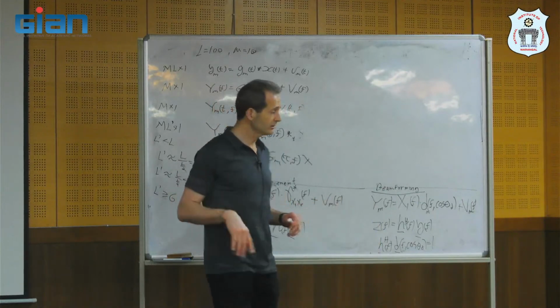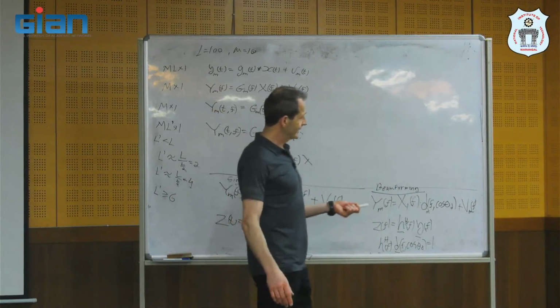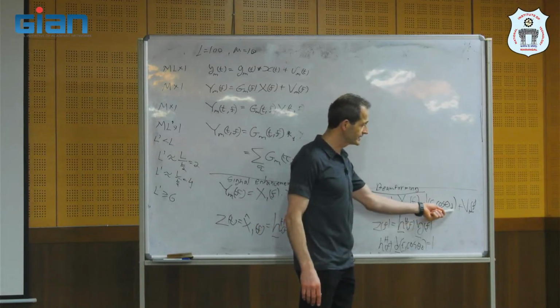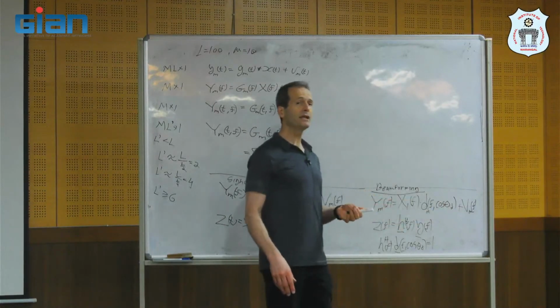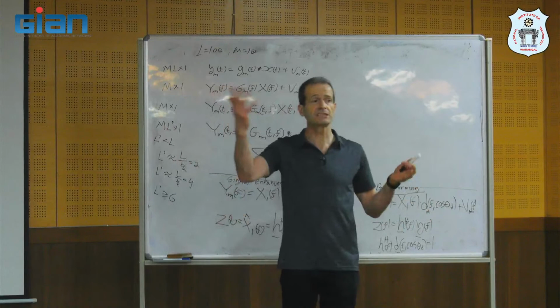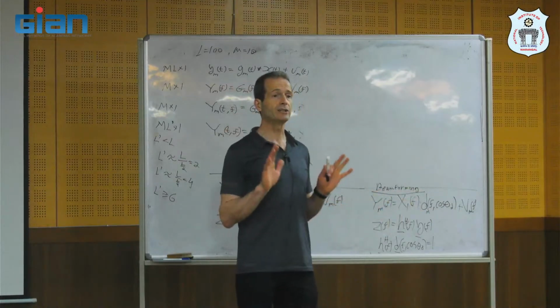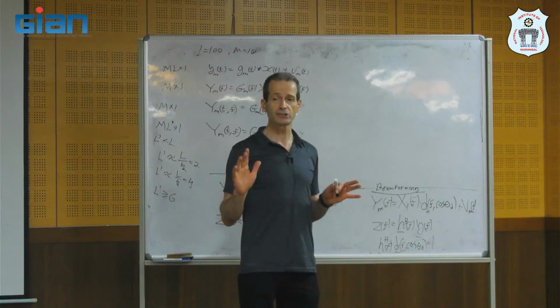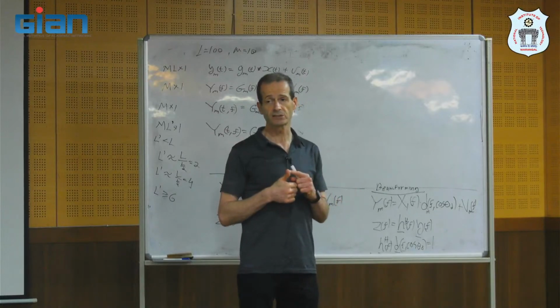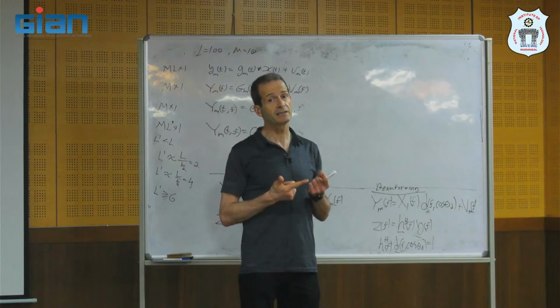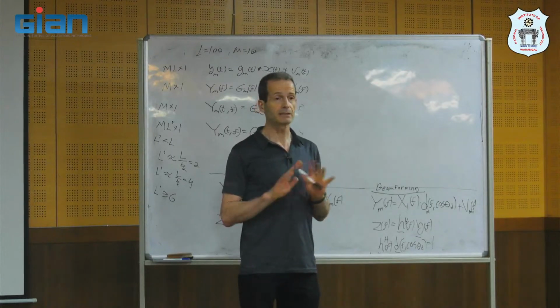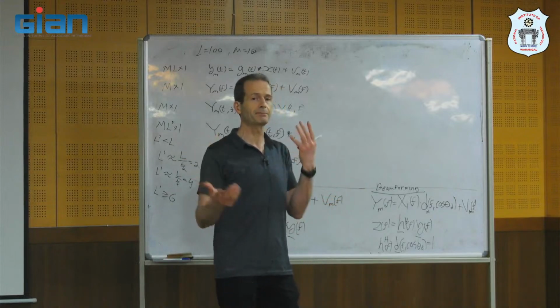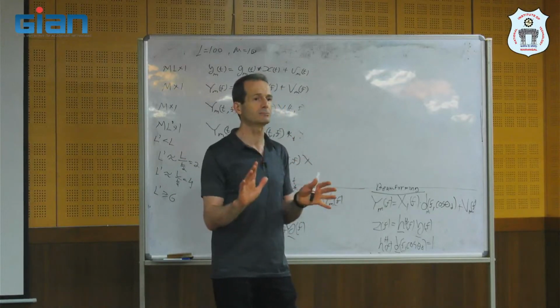I only know that the desired source comes from this direction, and maybe I have undesired interferences from certain directions. So I know only information about directions, the direction of the desired source, and maybe directions of undesired interferences. But I don't know what type of noise, what is the statistic, correlation matrices, and so on.